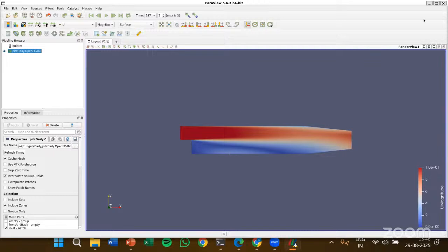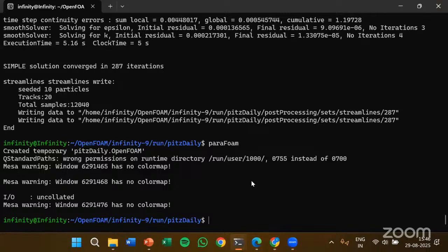So yeah, these all are there just to check whether your installation is done properly. Because sometimes when you install OpenFOAM, if you're on Windows 10 or any older version, when you install it using these commands, sometimes it may give you an error, like your ParaView might not load, or your OpenFOAM is not installing properly. So as I said, YouTube is your best place to search for a solution.